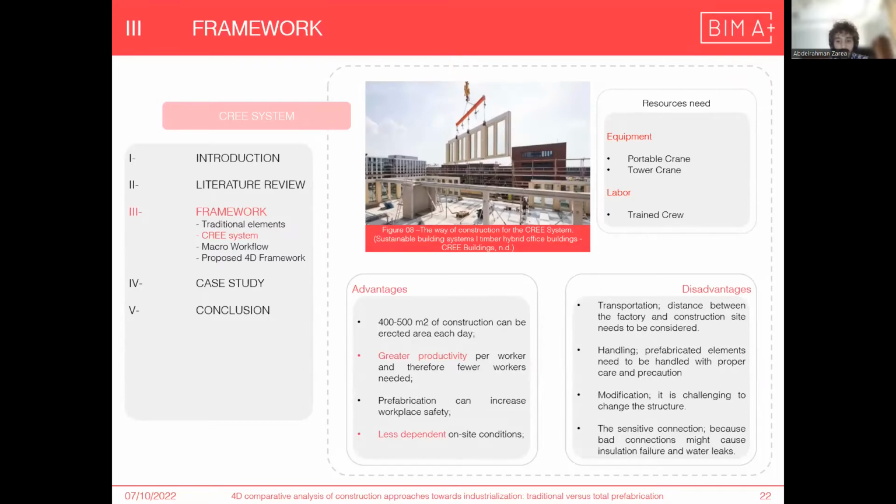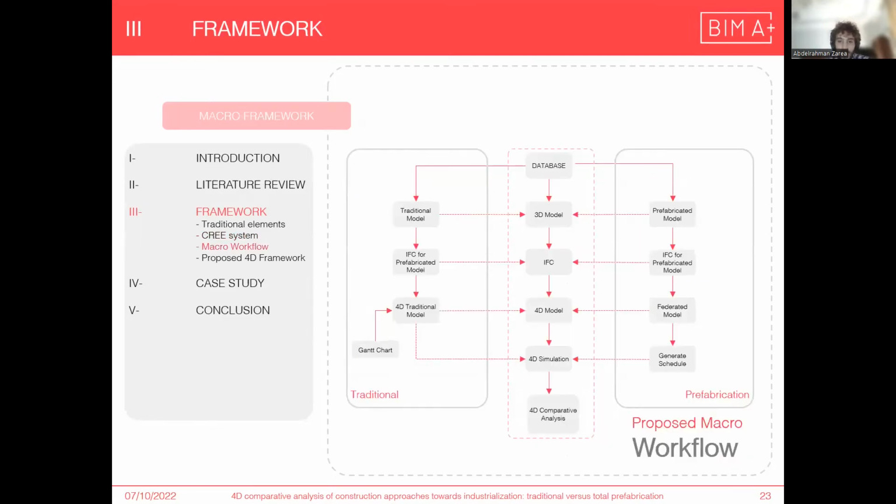Prefabricated elements need to be handled with proper care and precautions. As a macro workflow for the goal of the research, we need to define the database that is going to be used to start the 3D modeling, export the IFC to start the 4D modeling in any 4D software, making the 4D simulation by assigning the schedule for the work, and reaching the 4D comparative analysis between the two types of construction.